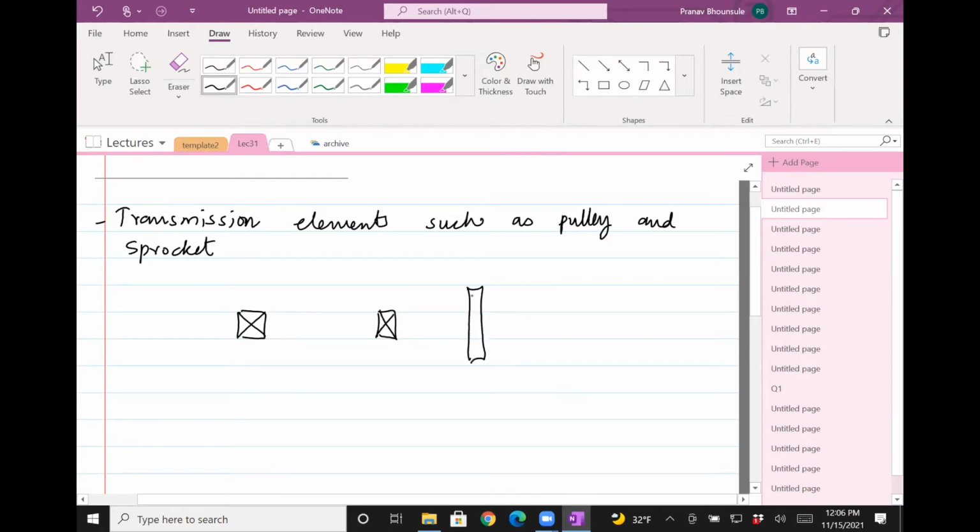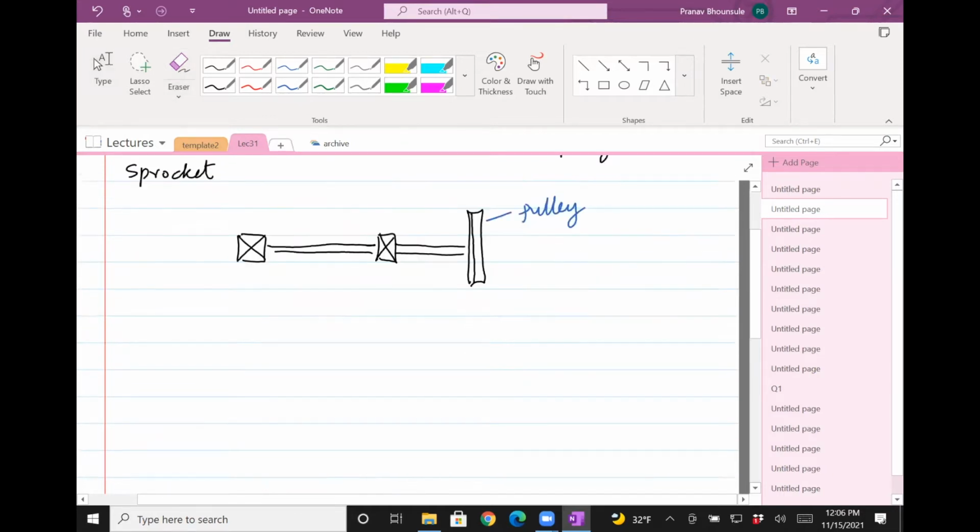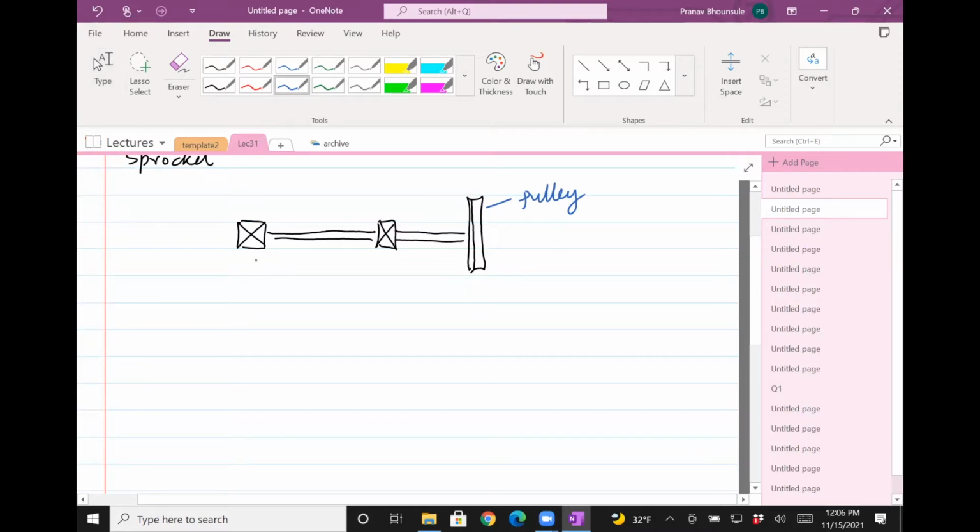This is, in this case, a pulley, but you could put a sprocket too. Okay, so why do we put a pulley or a sprocket on a cantilever? It turns out that you'll mount these things on belts or chains, and when you want to do that, it's much more convenient to have a cantilever so that they don't really hinder the bearings. Right? If you put it in the middle, then it's just a hassle to put the chains, sorry, the cables or transmission elements on them.